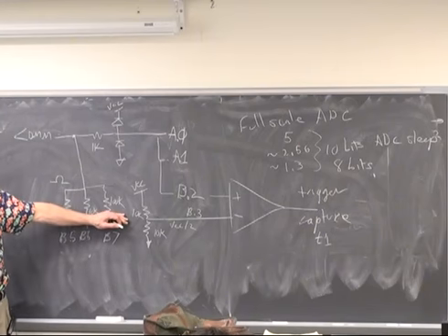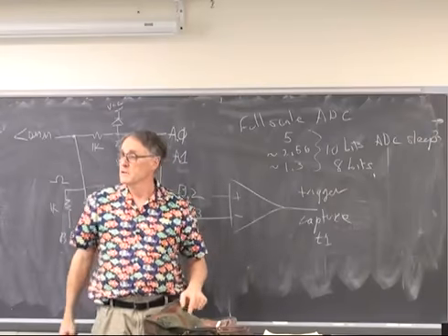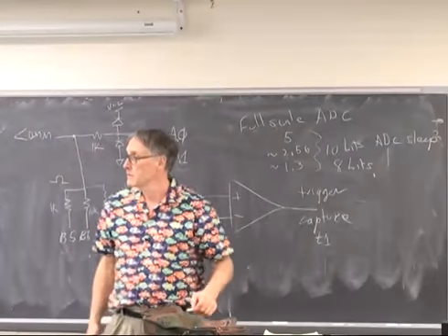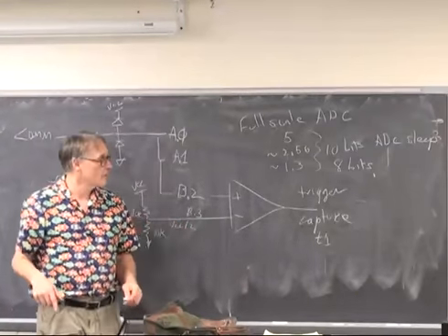Circuitry's easy. Just resistors, a couple of diodes. Of course, you do have to wire up the LCD still, and you're going to have to connect a keypad, a 16-pin keypad, which we're going to have to talk about. It's a 4x4 grid of switches. So there's a grid like this, a 4x4 grid, and every intersection has a possible switch point on it. And you have to be able to decode that. We'll talk about that code in a little while.